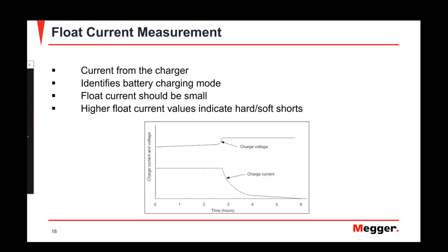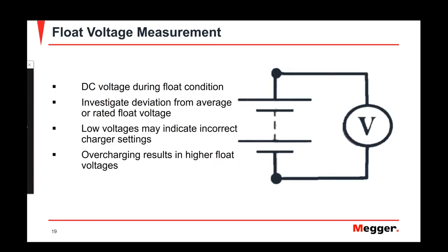Now, what you can do for this is, this is a sign that we do need to take some impedance measurements to help evaluate our battery string. And this will allow us the opportunity to narrow down why our system is experiencing higher float current conditions. So, strap resistance,